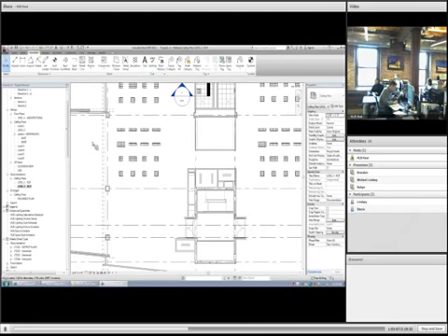So when we copied that group to other floors, that's then connected. It's all still connected, yeah. So we change one, it's changing them all. In a loose way, you can think of it like an XREF, where once we get a new XREF from a client, it updates in our drawings. Well, I would think it was more like a block. Yeah, or a W block, where you redefine that definition and then it's taking it through everything. So where you have that very repetitive stuff, it's helpful.